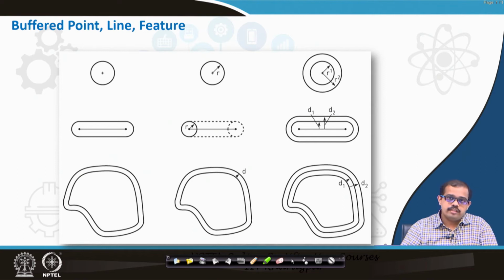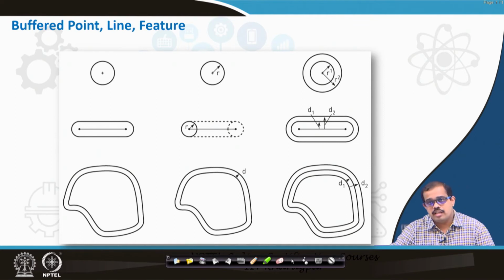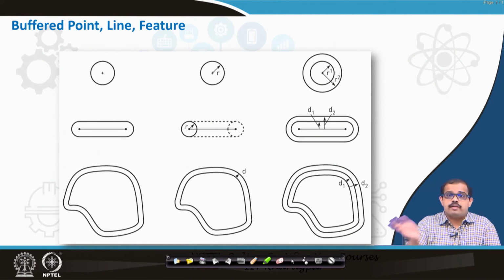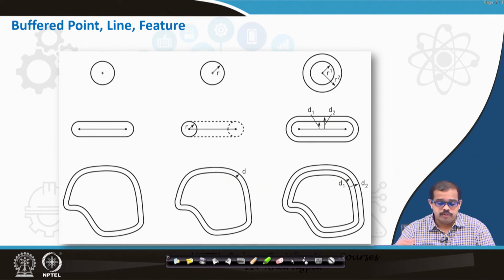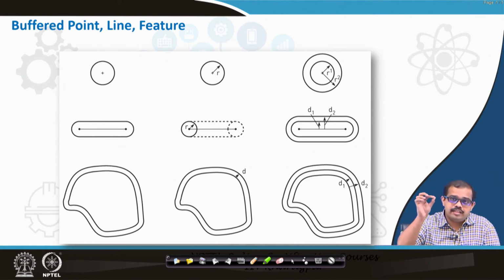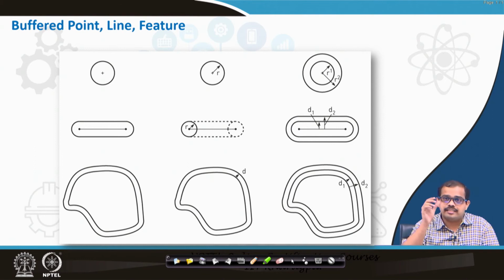So, now with different phenomena because of different decisions by the government, there may be a spread in different regions. Then you had national highways, then you have your state highways. Based on this there may be a spread outside the city boundary also. So what you do, you have a 2 kilometer buffer or a 5 kilometer buffer or a 10 kilometer buffer. Once you have understood that, then you can find out at every instant, at every buffer that you have considered, exactly where the urban area is intensified.